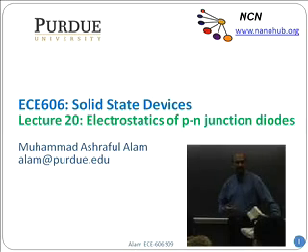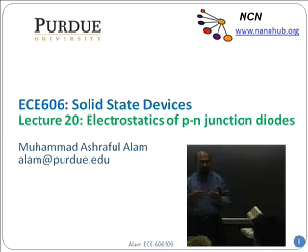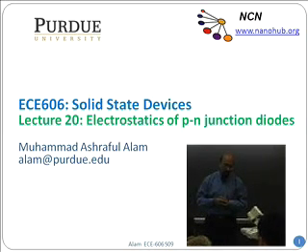That simply says that we don't really have to think about all the states, but rather compress all the states into one state near the conduction band edge and another at the valence band edge, and that's about it. And then we talked about how electrons are distributed within those states: Fermi-Dirac statistics. And from that, we did the transport equations. I showed you two examples, analytical and numerical, of how to solve them. So that was the first 5 weeks, that's the foundation.